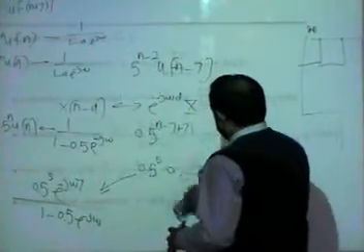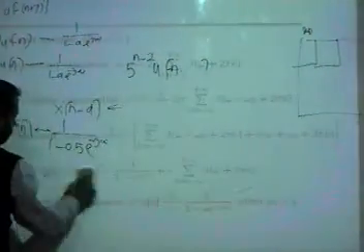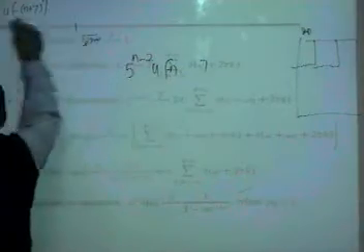All these pairs are important from several perspectives. Though these are just formulas, their significance is that, especially in the book, you will find plots of the magnitude response and the phase response of 1 over 1 minus a exponential minus j omega. Okay, you look at the plot, you will find the magnitude is a low pass, but the phase is nonlinear. They'll help you comprehend that an IIR filter will have a nonlinear phase.